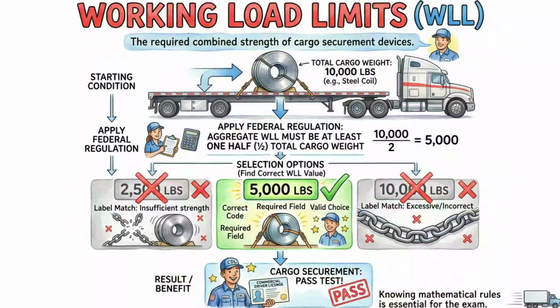Passenger management also involves dealing with disruptive individuals who could distract you from safely operating the bus. If a passenger becomes aggressive or heavily disruptive, your primary duty is still the safe operation of the vehicle. You should never try to physically handle a problem while driving, but instead pull over to a safe, well-lit location before addressing the situation or calling authorities. The exam emphasizes that your attention must remain on the road, and stopping the vehicle is the only safe way to resolve severe interior distractions.